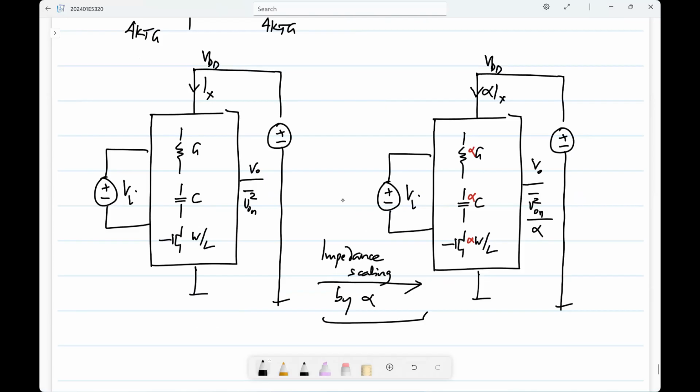So again, it's easiest if you think of two circuits. If you have two identical circuits, they'll have 2 times this one. Okay. So now if this is dissipating a power PD, this will be dissipating a power alpha times PD. Okay. So this reduction in noise doesn't come for free. It comes with a proportional increase in power dissipation. Okay. Is this fine? Right.